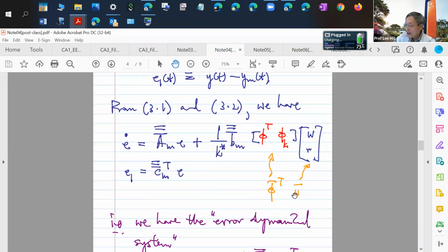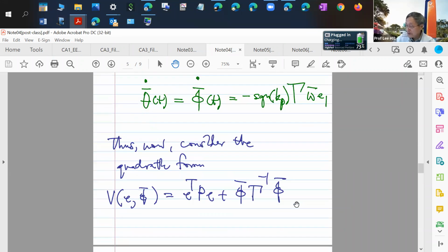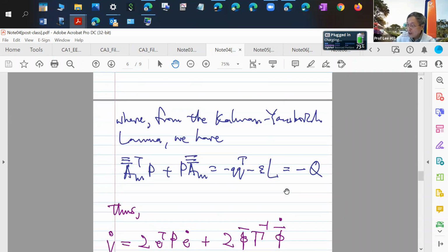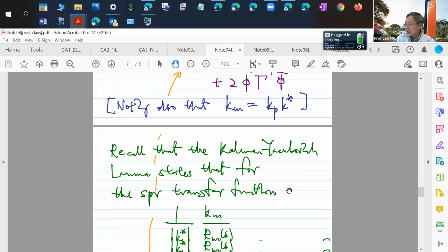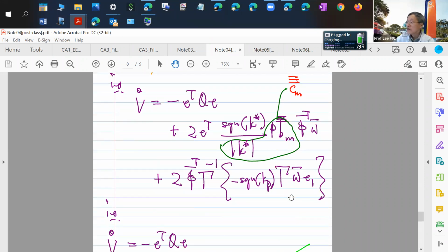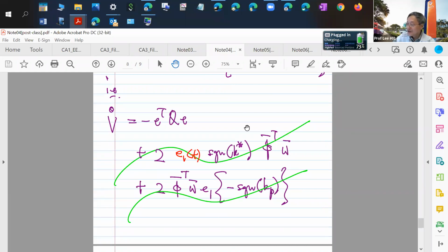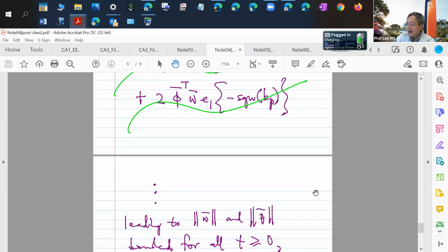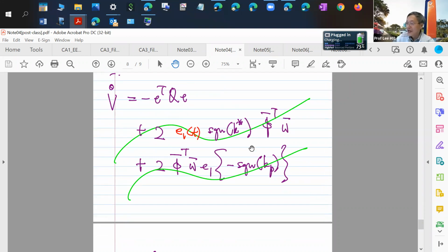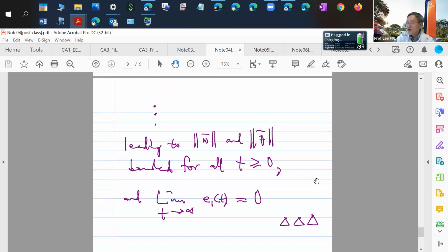So you can put together the error models. Then, noting strict positive realness, this will be the adaptive law. You go ahead, put those things together, carefully check all of that, and you begin to see that indeed all those properties are there, including, if you integrate the square of the errors down here, again you get the so-called Barbalat's lemma, and you can get tracking error equals 0.